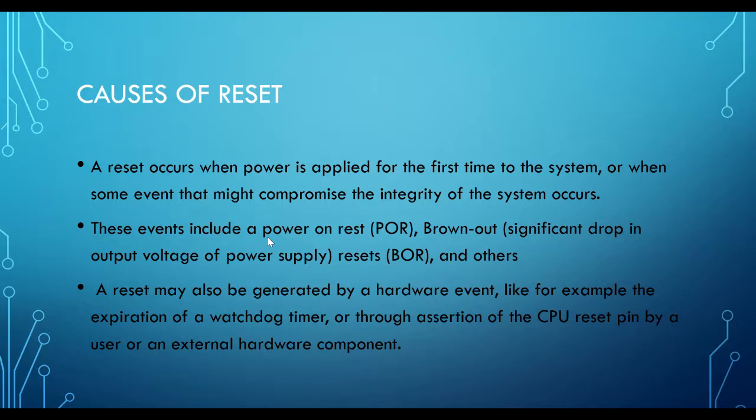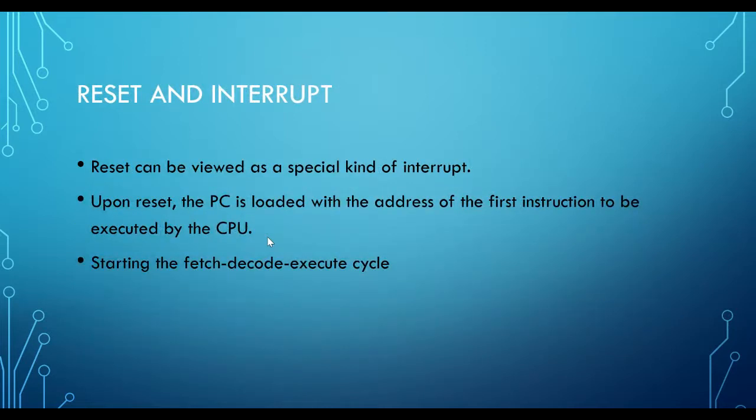The reset may also be generated by a hardware event, like for example the watchdog timer. So how do you detect that your computer is hung? Look at the watchdog timer. Reset can be viewed as a special kind of interrupt. The ISR is the action that you take, and instead of the LED, it is to move the PC to the reset address.